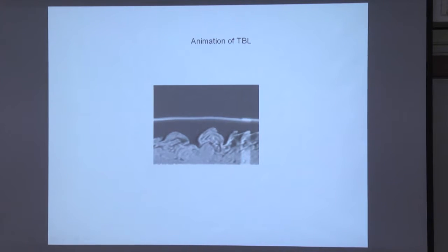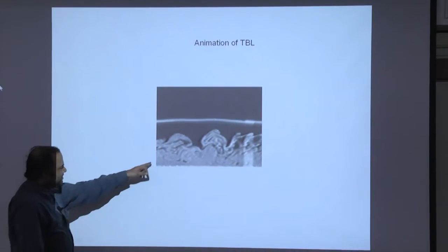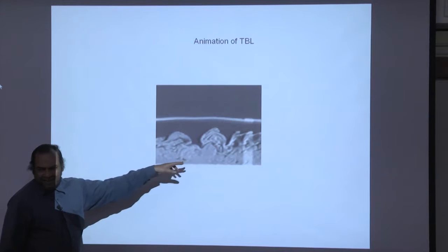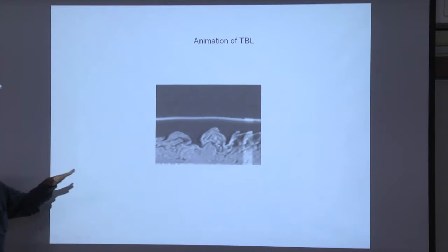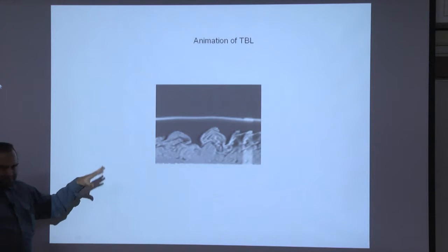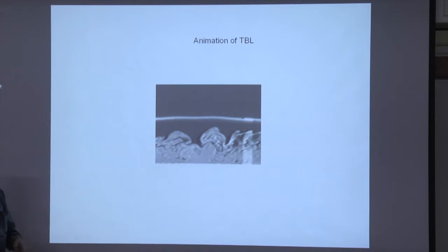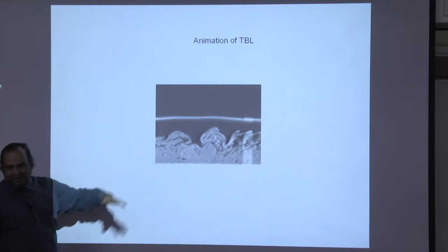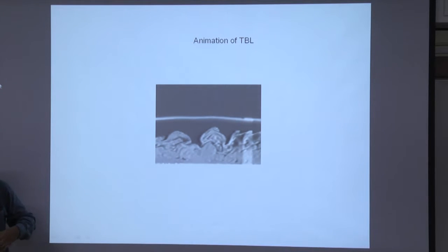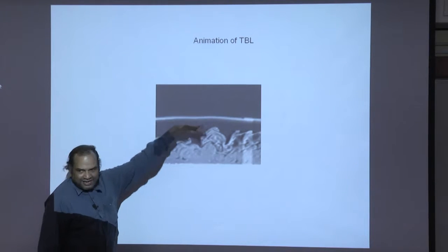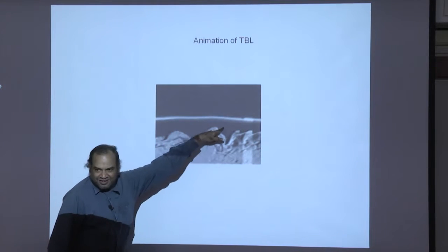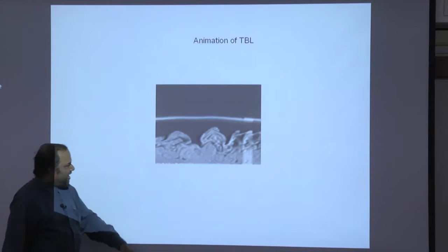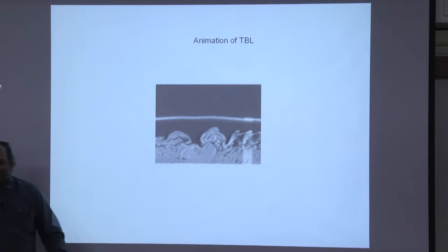If I could run that, what it would have shown is that there's a region inside the boundary layer. It's very dynamic. You'll see it moving in all kinds of crazy fashion, both spatially and temporally. That is of course the essence of turbulence. But a streak here in the outer region, outside the boundary layer, would of course meander like this, but it's a lot more ordered. It is not as confused or random as this.